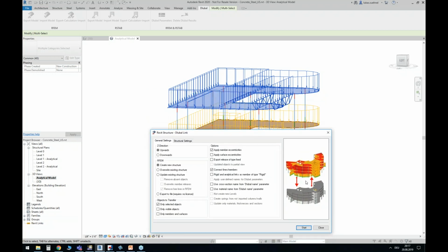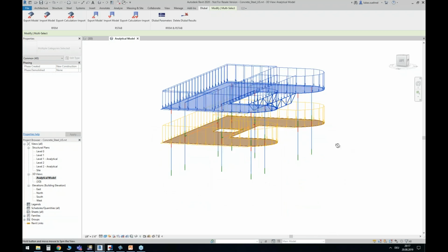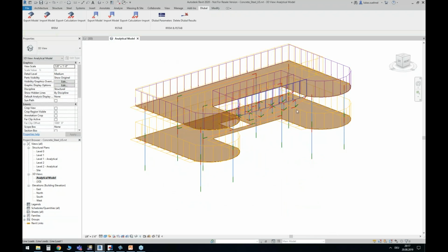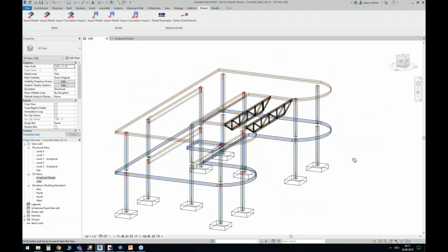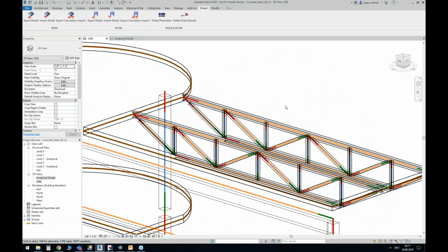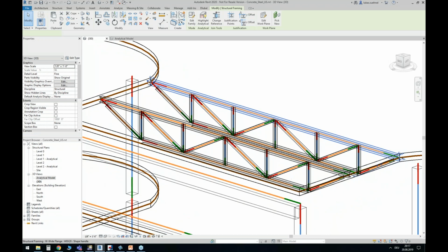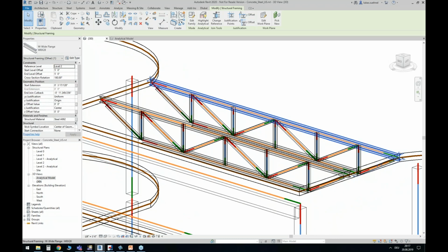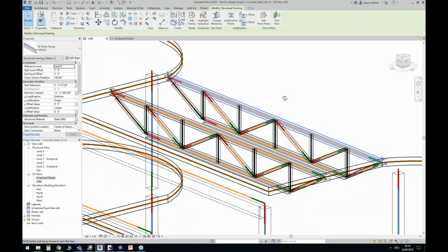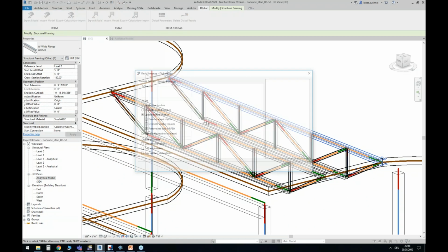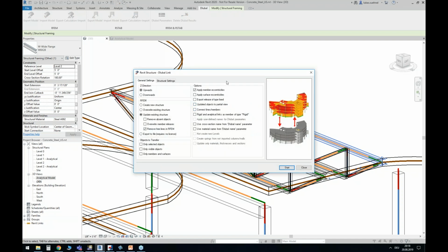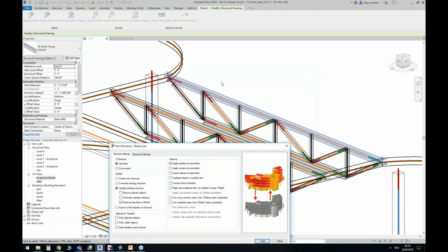I'm not sure if I showed it, because I forgot if I showed you or not. In that 3D model, I have this truss member, and the upper girder of the truss is one member. Yeah, I think I showed you. It's not divided in any of these nodes. So this option, connect lines and members, controls what's happening when you export that type of structure, for example, to RFEM.